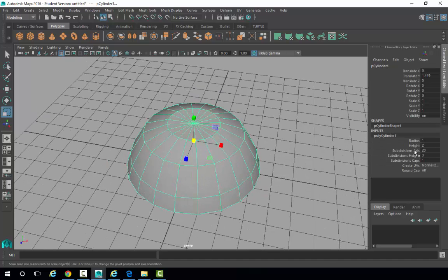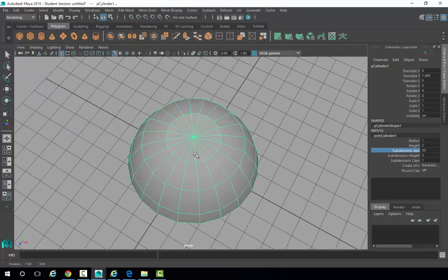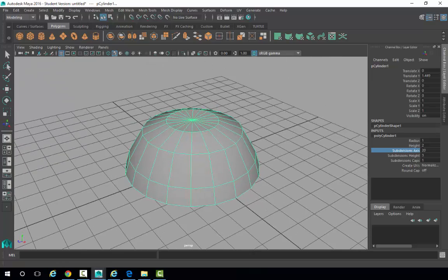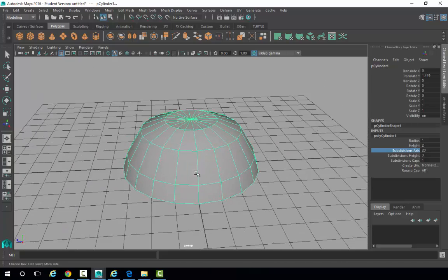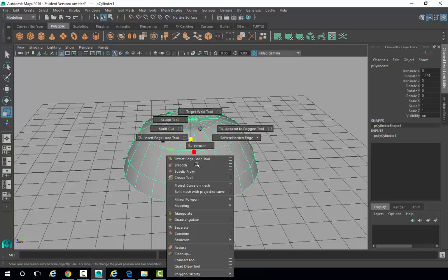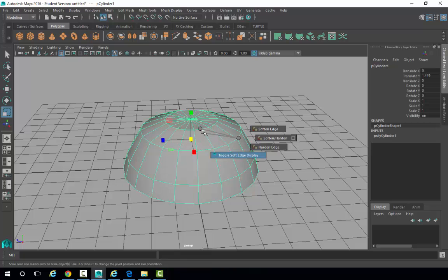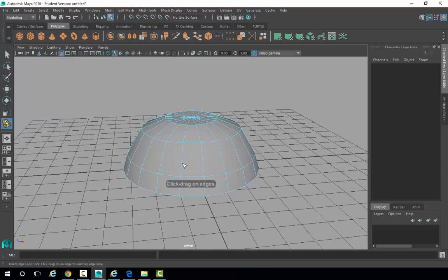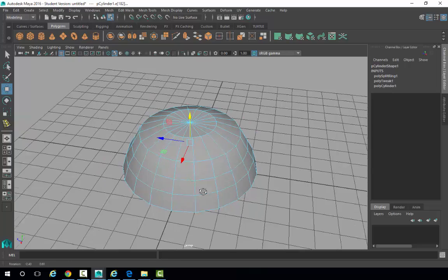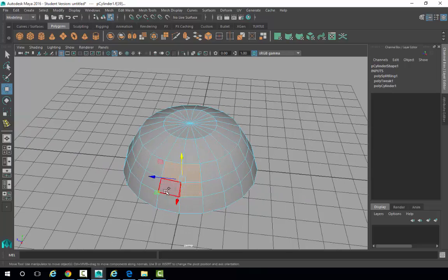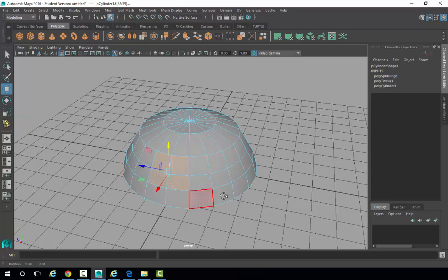Now if I start changing the shapes, obviously this is going to cause me all sorts of problems, so I'm committed to 20 subdivisions on this, but I believe I'm probably going to need them anyway to make the handles points. So I'm going to start with the handles. I'm going to put an edge loop in here. So the edge loop is actually on this side, so we'll just pop the edge loop in there, and that's going to create a set of 4 faces that I'm going to use.